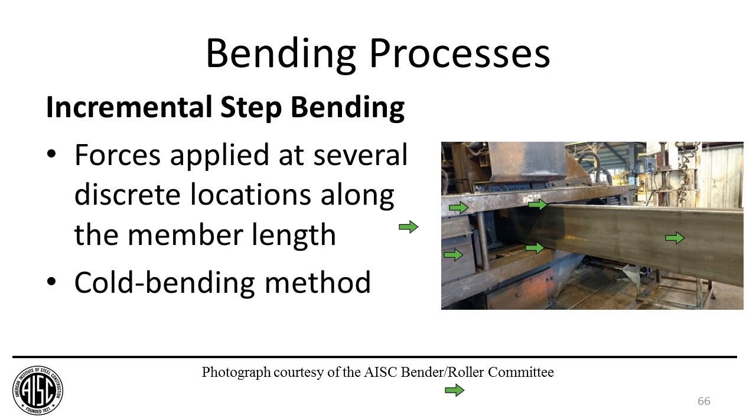So it pulls back, and back behind the figure the member is clamped, so you get a cantilever bending type action when the machine pulls in that direction. All right, so you pull that member, get the cantilever bending action, and then it releases, and then you feed it through again, and you do the same thing. You incrementally feed this thing through and pull on it until you get the correct shape of member that you're interested in.